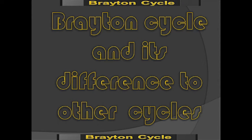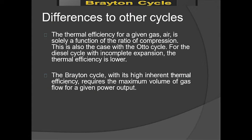So, the Brayton cycle and its difference to the other cycles. The thermal efficiency for a given gas air is solely a function of the ratio of compression. This is also the case with the Otto cycle. For the diesel cycle with incomplete expansion, the thermal efficiency is lower. The Brayton cycle, with its high inherent thermal efficiency, requires the maximum volume of gas flow for a given power output.